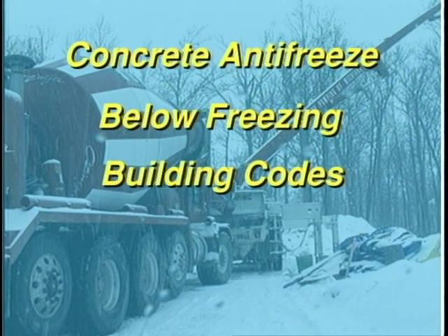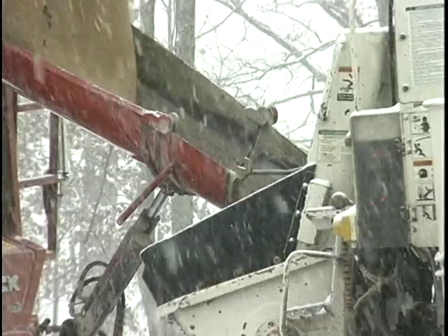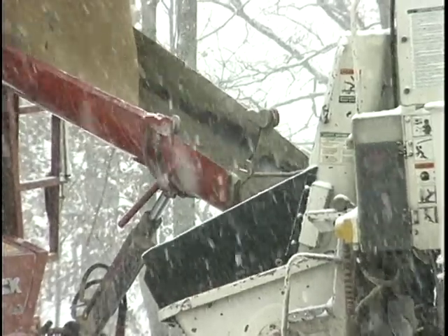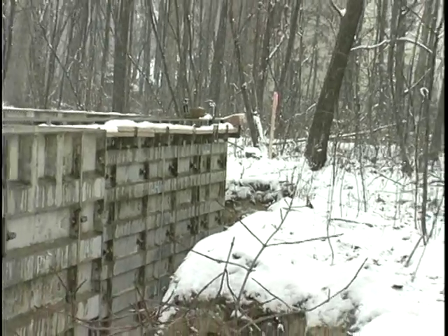Local building codes will limit the lowest temperature possible during a pour. Generally, avoid pouring a foundation in temperatures below 20 degrees Fahrenheit. Below this temperature, even additives will not protect the concrete from freezing and structural weakening.